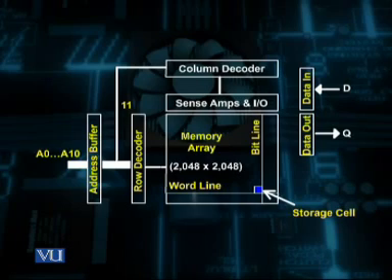For example, in this block diagram, you can see that the cells of a 4 megabit DRAM are organized as a 2K by 2K bit array. Furthermore, the addresses are divided into 2 parts, that is, the row address and the column address. One of the addresses is sent at a time to reduce the number of address pins.